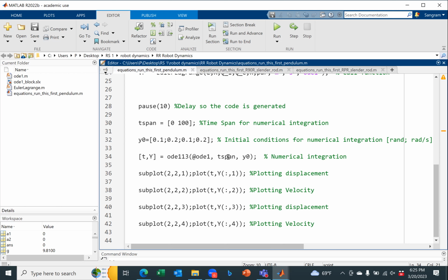Even though you shift the frame, you are not shifting the mass. So that doesn't matter. You will solve forward kinematics exactly the way we are solving, and once you get Px, Py, Pz for all the masses, take the derivative and solve the problem. You don't take the shifting into consideration. The mass is not going to change. Let me take an example, and that would make things clear.